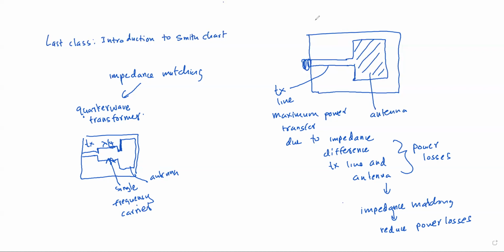For applications where we need to use the same antenna for different frequencies, we might not be able to use this kind of matching circuit. In that case, we need to go for other options where we can use the same circuit for different frequencies. In those circuits, we use stub matching as the matching technique. Stub matching is done with the help of Smith charts.